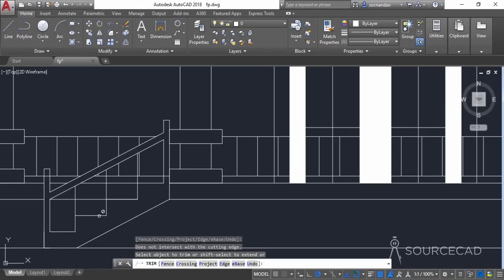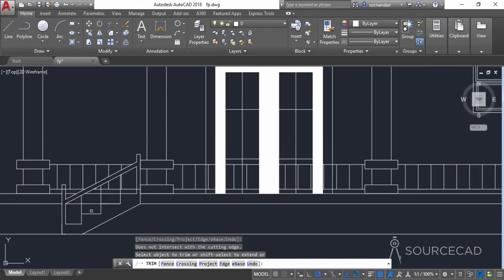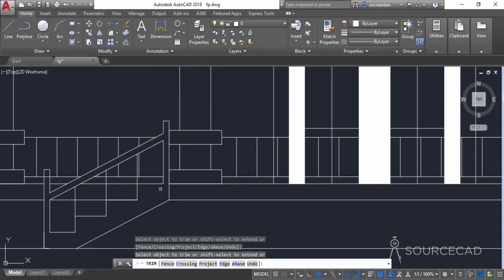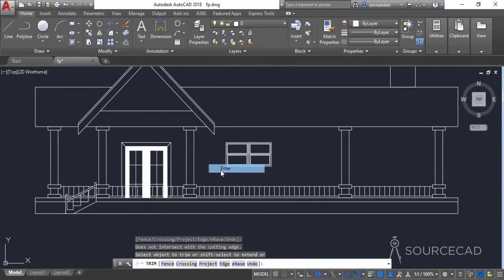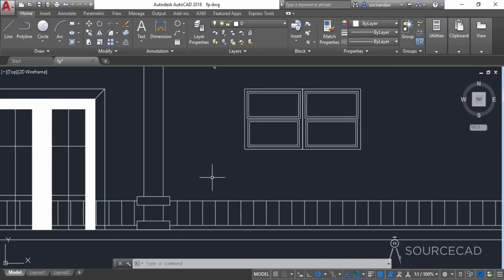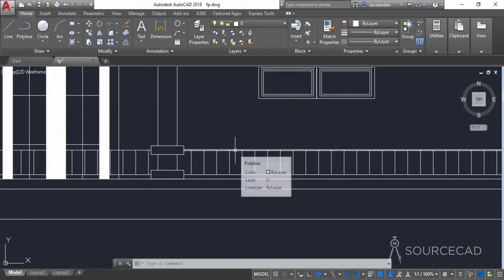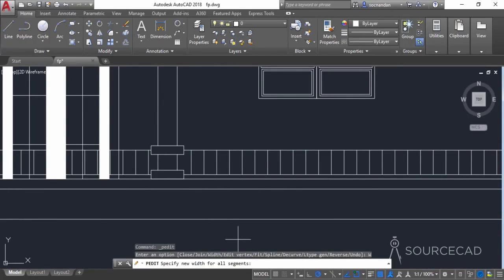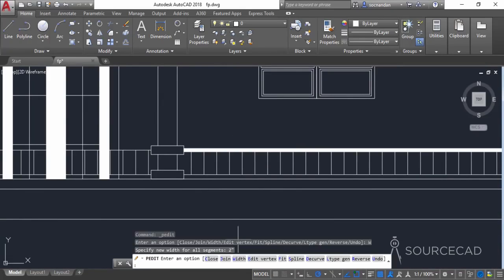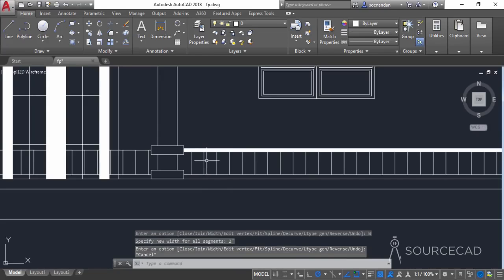So that has actually cleaned our drawing pretty much. Okay, this is something that we need to take care of. Okay, so that's it. Now we need to add the thickness to these polylines, and that can be easily done with the help of width tool. So simply double click on any one of these polylines, maybe this one. So double click there and go to width option. Now enter the width. In this case, I'm entering a width of 2 inches and press enter, and just look at this. So the thickness is added here, and you can then copy this property to other polylines.